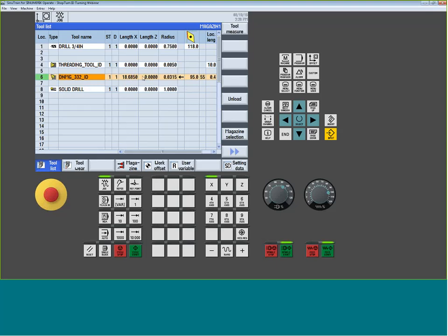Now these could certainly be a distance from a gauge line. It's very, very common in lathes, especially slant beds, that things are built relative to the turret faceplate. So in that case, you potentially could see some very small values here. But then I would have to shift things with my work coordinate system. So there's two real methods of setting up lathes. Do I want to have everything established from machine 0 for my tool lengths? And there'll be large values, positive or negative, it depends on where the machine 0 is.